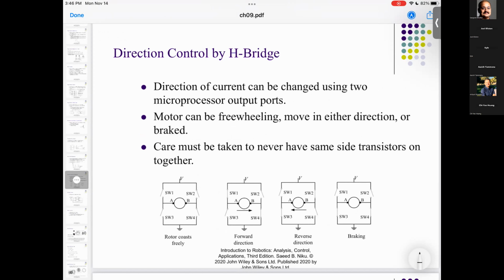Okay, so you are able to do forward kinematics, then you can do inverse kinematics, and then at the end you can find the kinetic energies and you can find the potential energies. And after you use the Euler-Lagrange, you should be able to find the Lagrangian, which is the difference between the kinetic energy and potential energy. So T minus V. Any questions here?